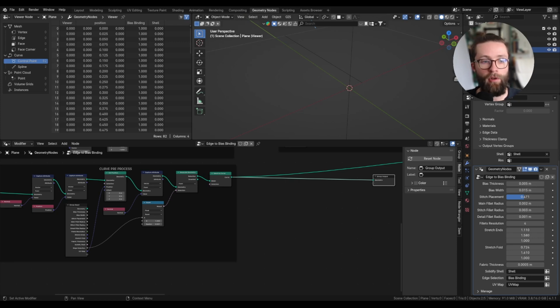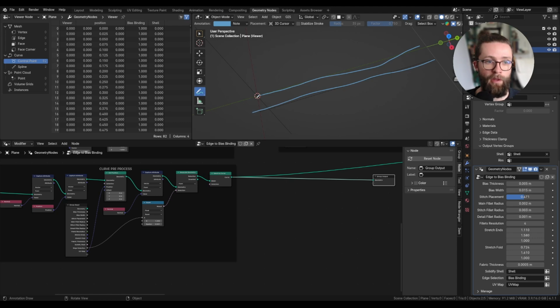So now with our curve in UV space, we have one more problem to fix before moving on with everything, and that is that the direction of our curve may be inconsistent because of the way Blender converts a mesh to a curve. So right here I have my curves here and here, and ideally if the mesh is on the inside, we want the direction of one curve to go in one direction and the other in the other direction, so that we have a consistent outwards direction, but it may not be the case.